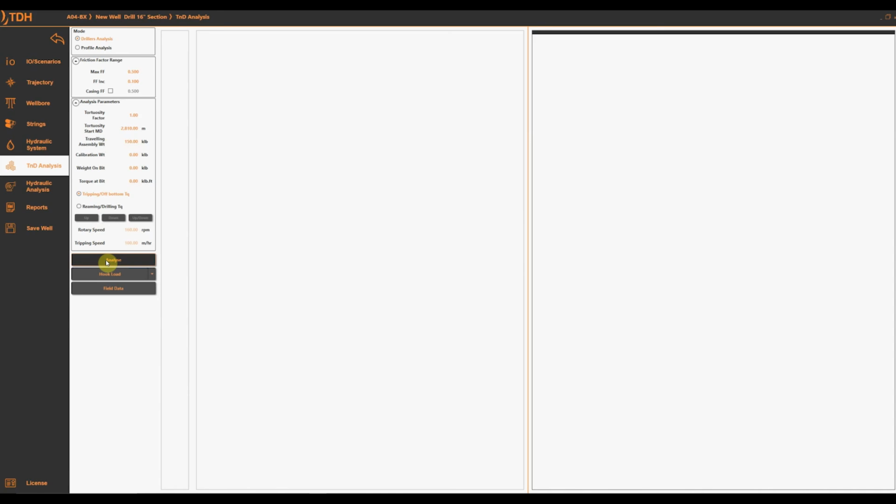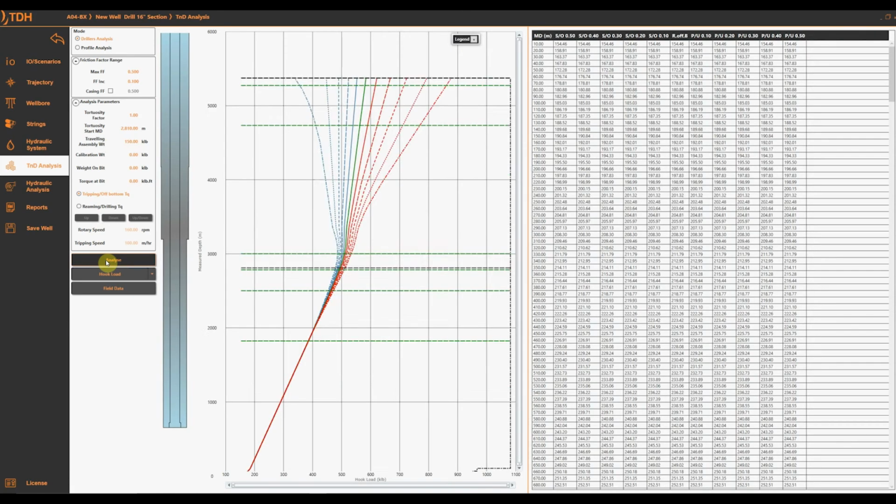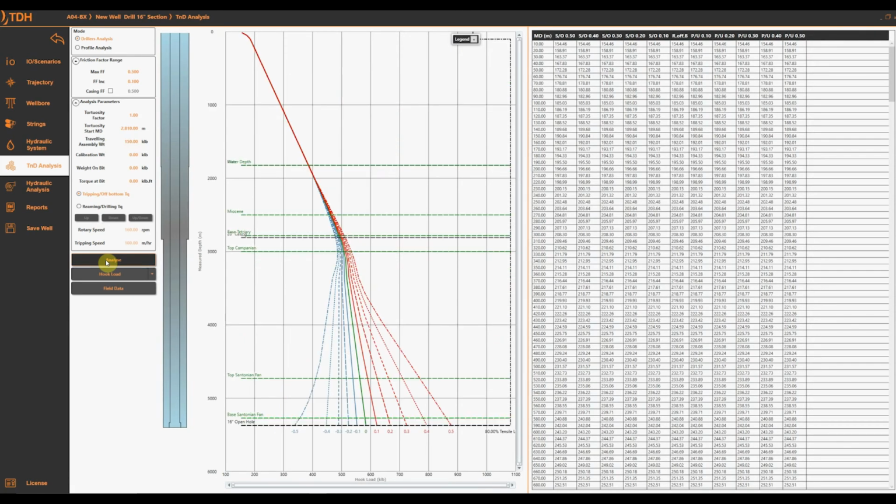So from the past well, from the hindcasting, I know that I will be following roughly 0.3 friction factor lines, which is this for pickup and 0.3 for slack off. I'm also plotting here 80% of the tensile limit, body, sorry, and I can see that for 0.3, I still have plenty of overpull available between my load line and my tensile limit. For slack off, I don't see any lockup, I don't see any buckling going on.